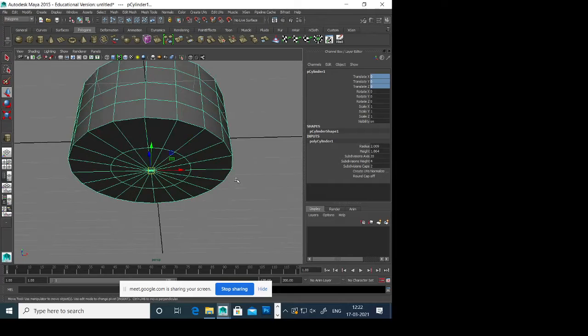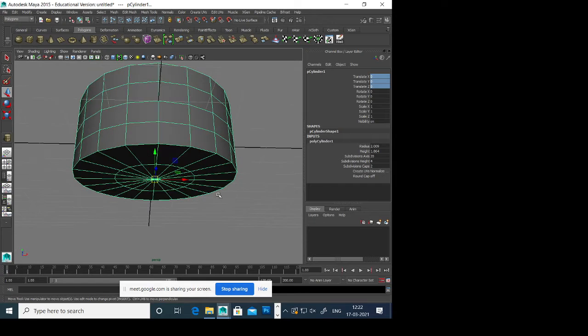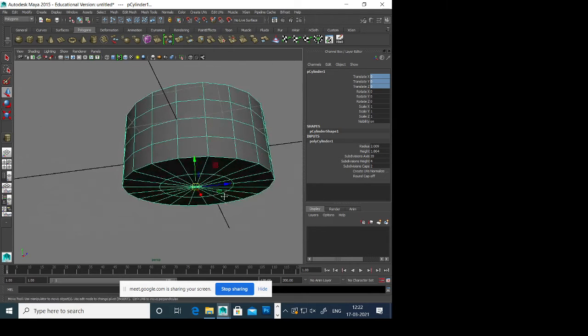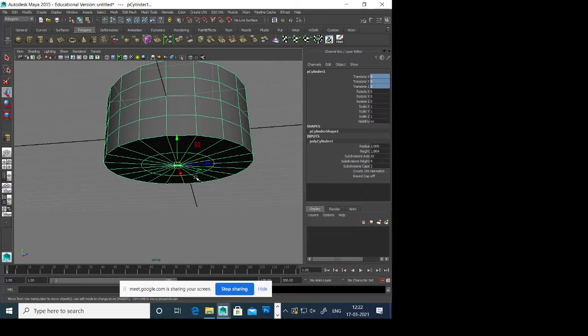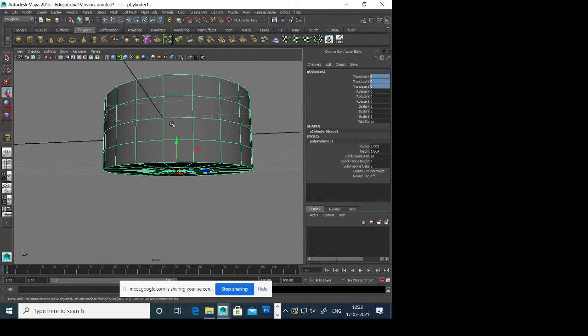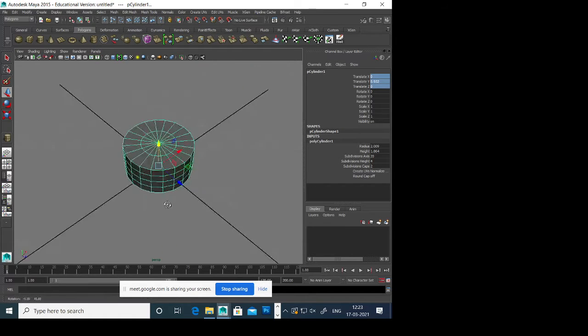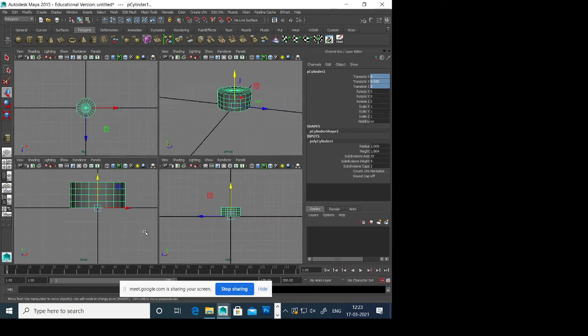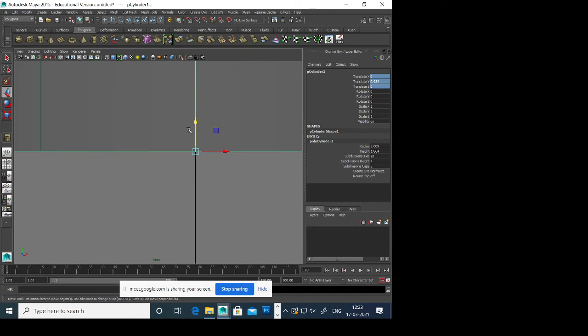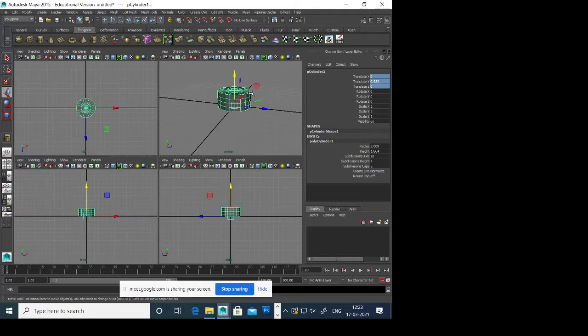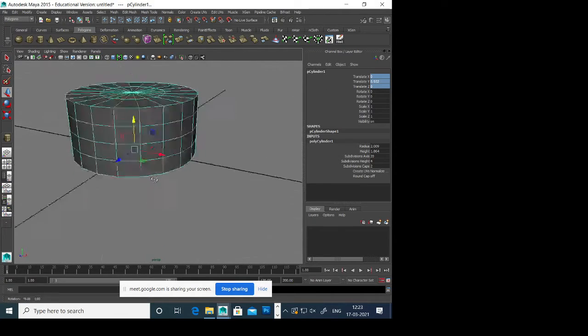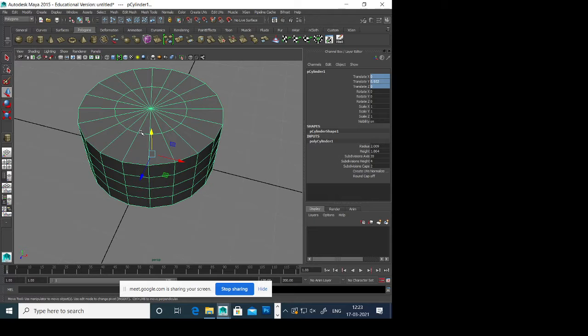instantly. So it becomes really handy to move your pivot and change the orientation, and it's really easy to snap wherever you want to. And this is how you snapped your pivot point on this vertex. But what if I want to move it to the grid origin, 0 0 0? Then you have to press X, click this, done instantly, perfectly. You can see perfectly snapped. So it's really fast and convenient. Like this, we can snap everything and create everything.